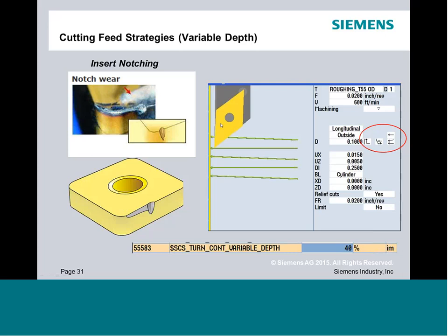So what we've done is we've created a function called variable depth cutting. And that's triggered right here by these little icons. This is where guys always miss. Usually they have this second icon here set to an equal depth of cut. But there's a way to set it up. If you toggle it to a varying depth, it aligns the depth up to some features. That gives you this third field. Once you do that, you can control the variable.